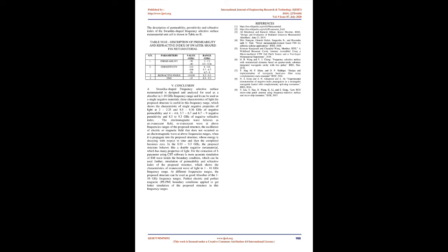The extraction of S parameters using CST software gives a more accurate simulation of the EM wave inside the boundary condition, which can be used further for simulation of permeability and refractive index of the proposed structure, which shows the characteristics of evanescent wave of light in the 1 to 10 GHz frequency range. At different frequency ranges, the proposed structure can be used as a good absorber of the 1 to 10 GHz frequency ranges. Perfect electric and perfect magnetic, PEPM, boundary conditions are applied to get better simulation of the proposed structure in this frequency range.